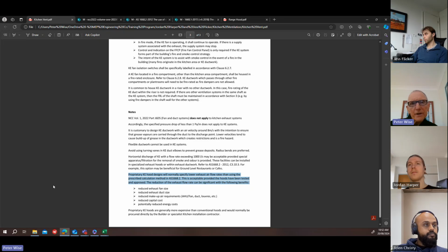and tested so that they're acceptable. They have to be tested and approved by the authorities, and you'll find that the ones that we deal with, the Stoddart's brands and the AOM, have all been tested. And they have significant benefits to the mechanical contractor. You can have a reduced exhaust fan size because you've got a lower exhaust flow rate, reduced exhaust duct size, reduced makeup air requirements, reduced capital cost, and potentially reduced energy costs.